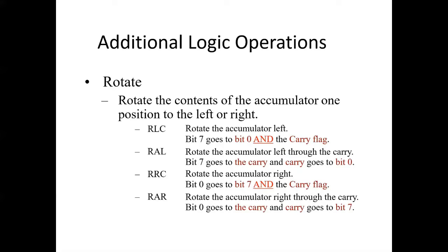We have to note that the carry flag is involved in the rotation, and it is a 9-bit rotation of accumulator and the carry flag contents. Only carry flag is affected by this instruction execution. This instruction is useful to check the value of MS bit of accumulator: perform rotate left, and the carry flag value is changed. It is also used to perform multiplication by 2. It works correctly for unsigned numbers as long as the MS bit of accumulator and the carry flag are 0 before rotation.